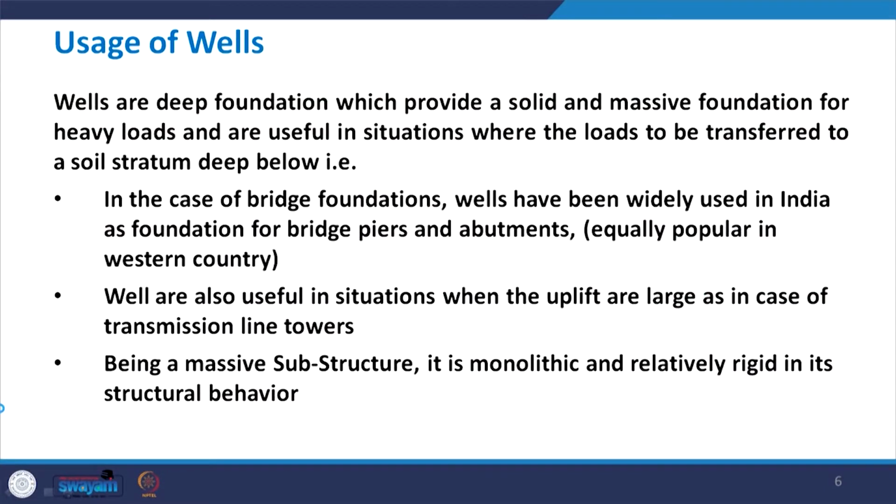So, the first one is usage of wells. As we discussed earlier, pile foundations and well foundations come under the category of deep foundations, and these foundations provide a solid and massive foundation for heavy loads and are useful in situations where the loads have to be transferred to the soil stratum deep below.